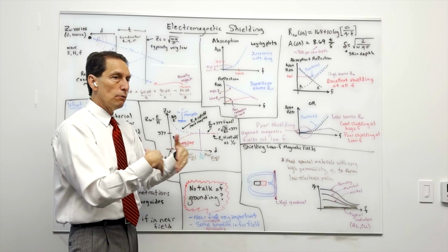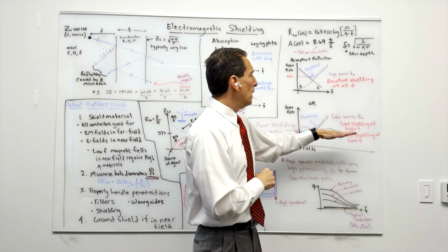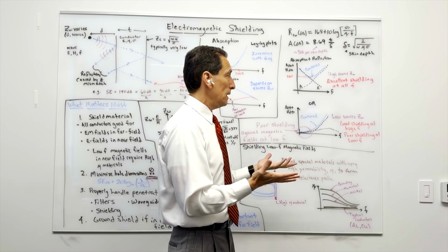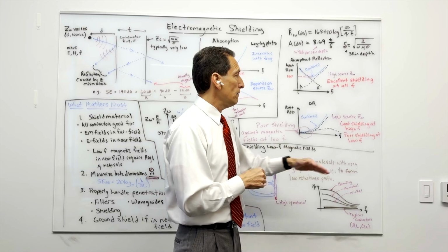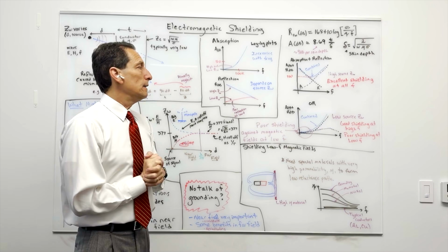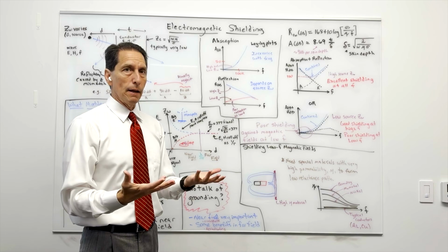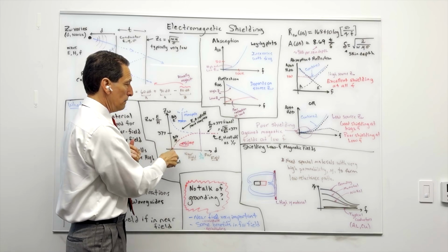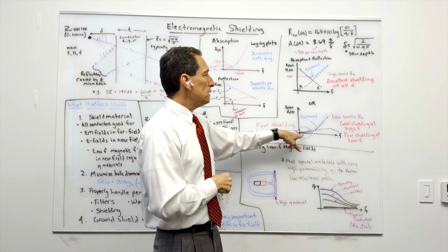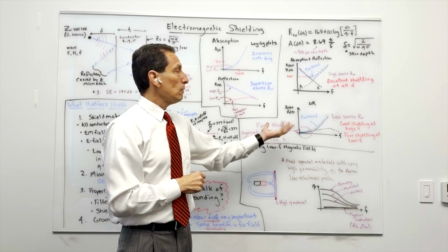Again, that loop antenna generated a magnetically dominated field when you're in the near field. So it does show that at high frequencies, you can block that incident electromagnetic wave, but not so well at low frequencies. And that's really where the rub comes in. When you have a low impedance source like a loop antenna, and you're in the near field, that means you're here. So you've got a lot of magnetic field compared to the electric field. The shielding doesn't work very well for low frequency emissions.